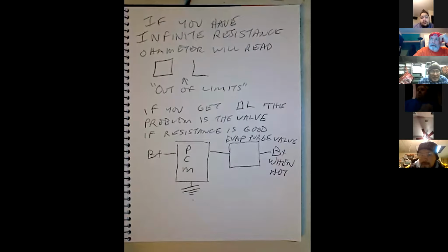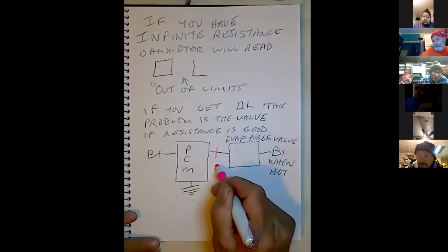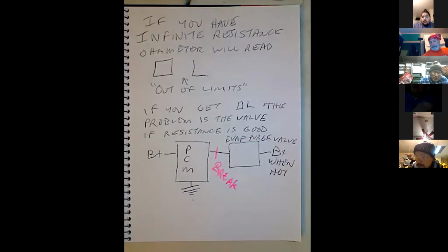Well, what about in the gas tank that detects the pressure? Is there an electrical connector there? Okay, here's what I'm going to do. The first thing I do is I'm going to follow Rudy's counsel, because I think that's a good one. First thing I would do is check the ground, and I would check the voltage, because this problem can be caused by, I hate to say it, a break in the wire. Yeah, broken wire. And if that happens, you're talking about rewiring that.